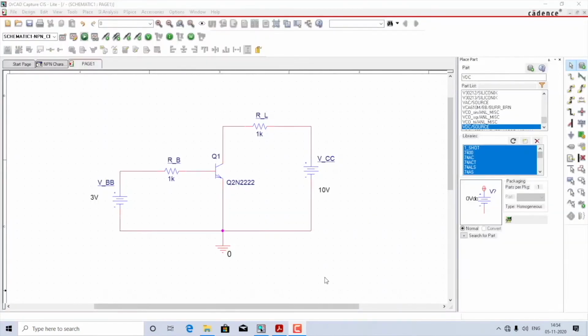Moving on to the output characteristics. Output characteristics are obtained by plotting the voltage across the output terminals, that is collector to emitter voltage, and recording the output current IC at a fixed value of the input current IB. We know that a transistor's output characteristics indicate 3 regions of operation: cutoff, saturation and active region. So, let me demonstrate the simulation of the transistor here by setting 3 different profiles for each region of operation.